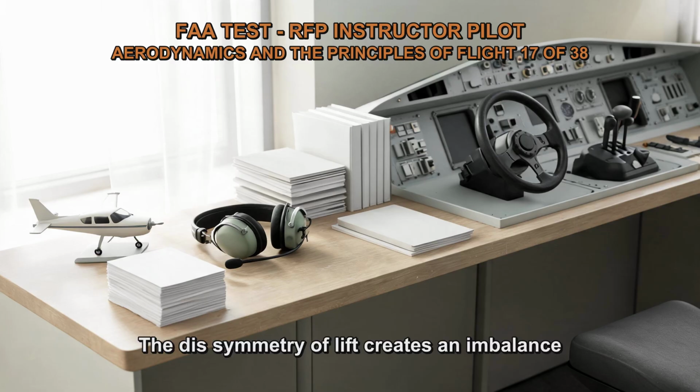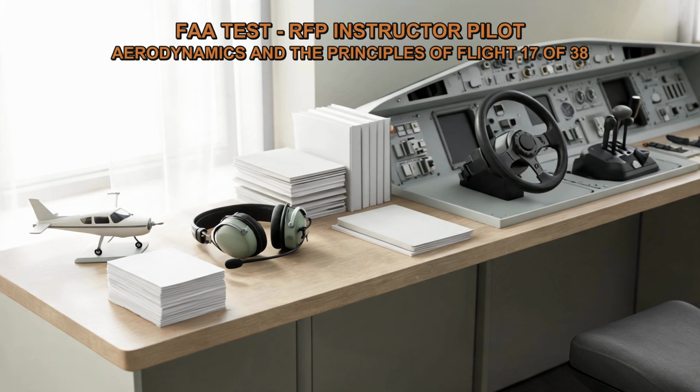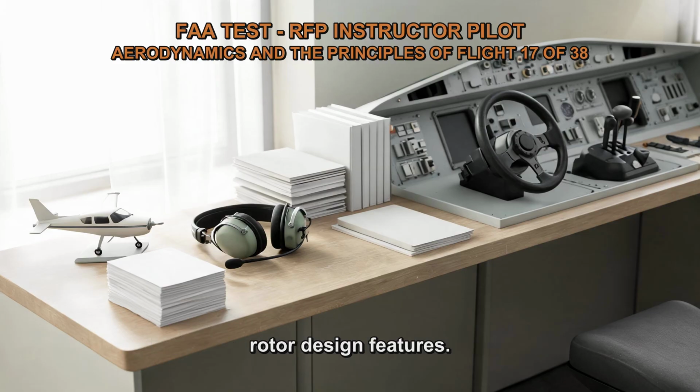The dissymmetry of lift creates an imbalance in the rotor system, resulting in a rolling moment that needs to be counteracted to maintain stable flight. Rotorcraft employ various mechanisms to mitigate this effect, including blade flapping, cyclic pitch control, and rotor design features.